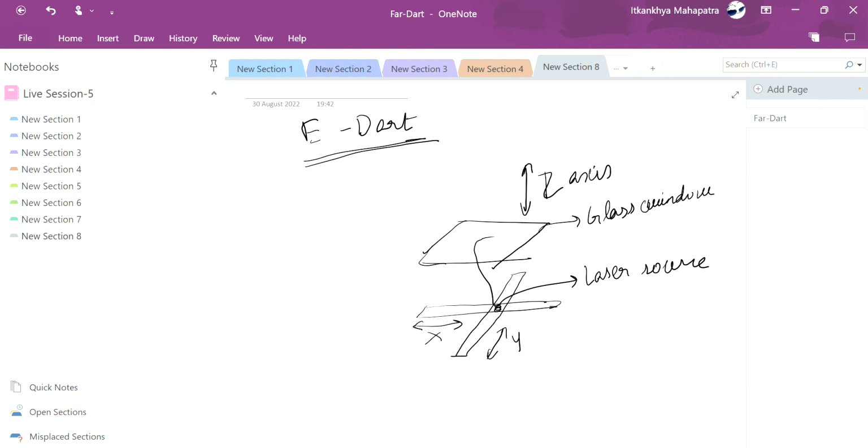This laser system is found under the resin tank. This is the resin tank. The laser beam is directed into the resin, which is in a container with a clear bottom plate. Now this system uses an acrylic resin. The model is formed by liquid resin, which is then cured by the laser light beamed from below the resin chamber.